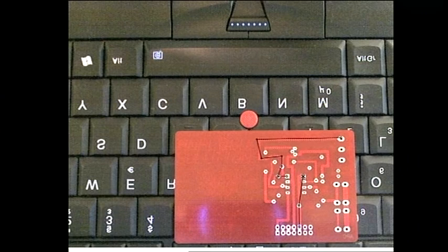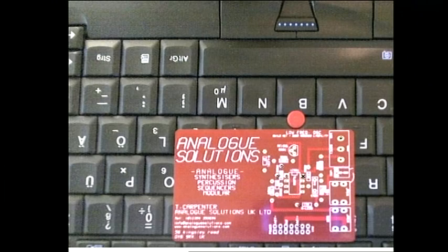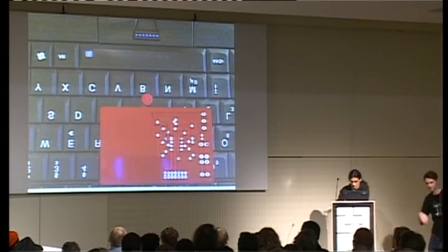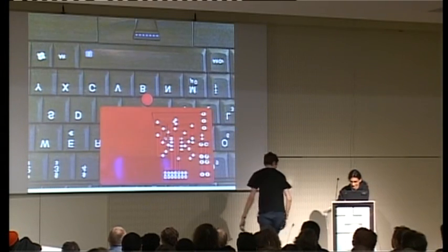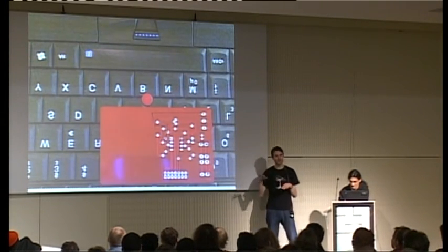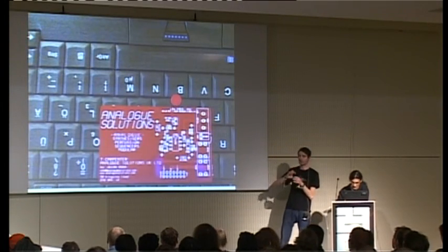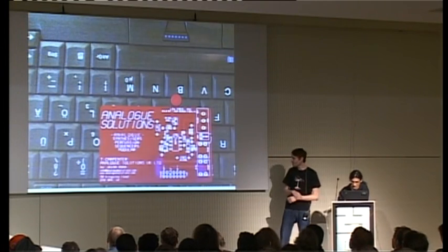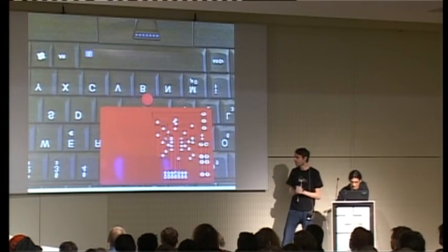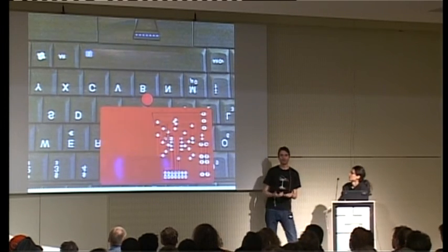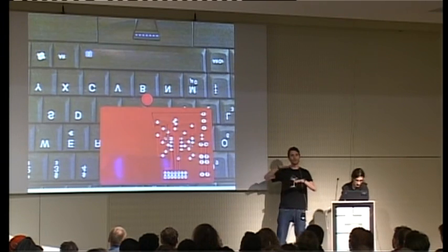This particular case might be just a 2-layer board, but in some of the devices that I've seen, even though there are multiple layers, whenever a trace needs to go up or down a layer, depending on the manufacturing style, you'll still have a full via going between all the layers that you can still tap. So even though you might not have all of the layers, you can still do some reverse engineering just based on the vias and the traces that you see on the top and the bottom.